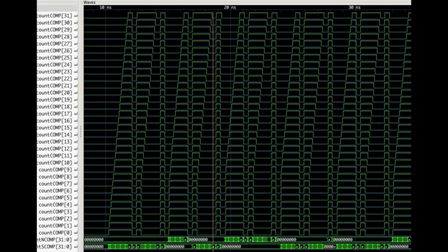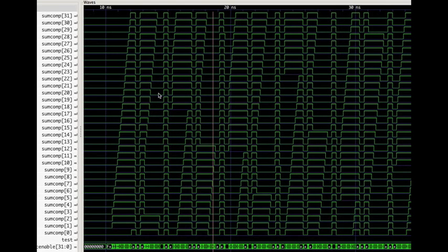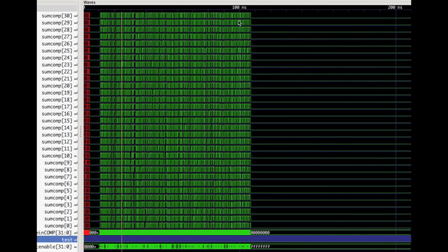Okay, so that was presented to the shifter, and this is the output of the shifter. Now you notice the discontinuities down here, and this is where the high order bits came down to present zeros as the low order bits, right? So this was a shift of 1, and this was the 0 shifted in from the high order bit to the low order bit. This was a shift of 3, and this is the 0 bit shifted in, and so forth. That's how the shifter works for the input of 2D pipeline flow.